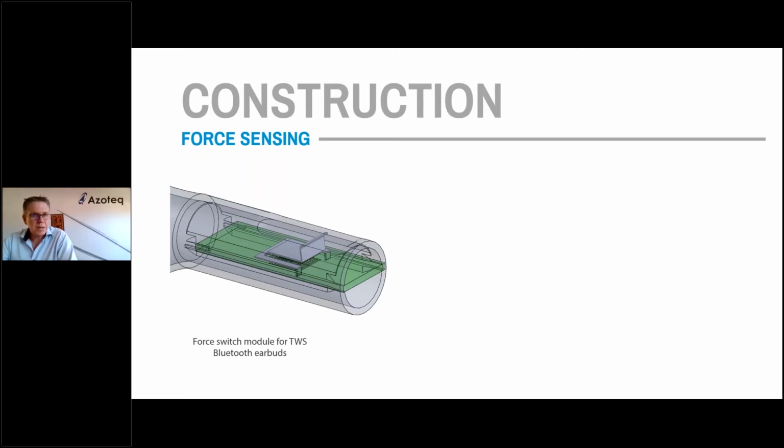So what we are proposing on the screen here is a spring-like structure that is hovering over the coil. Now, if you apply a small force to the outside of the stem, that spring structure will move closer to the coil, and we can measure that minute deflection. We can measure it with the inductive sensing technique.